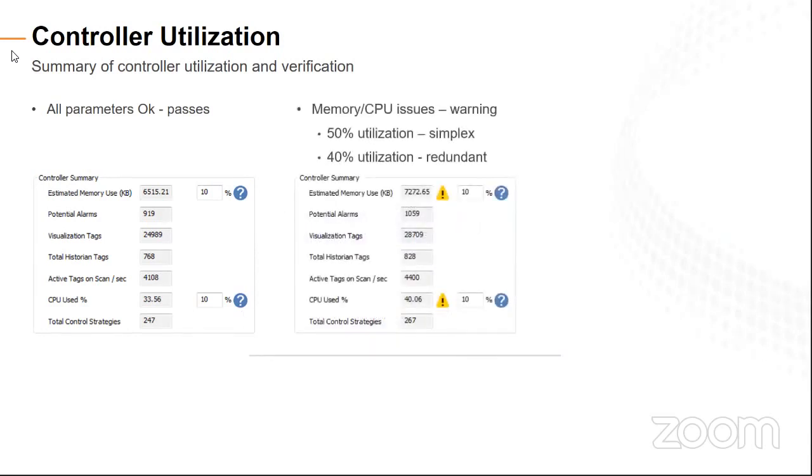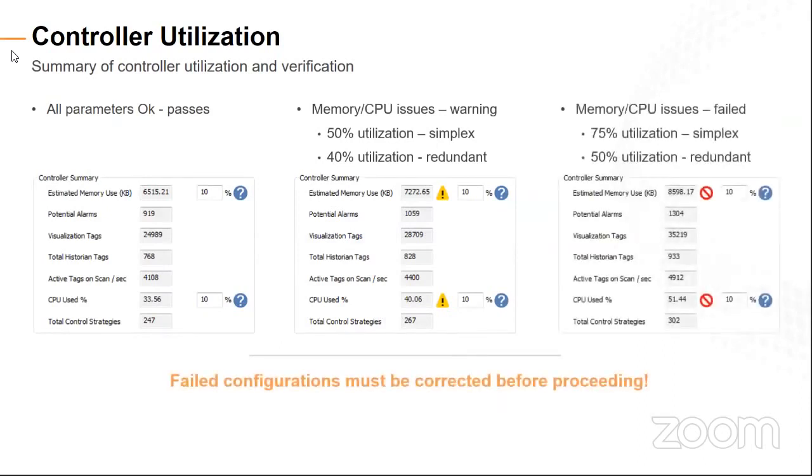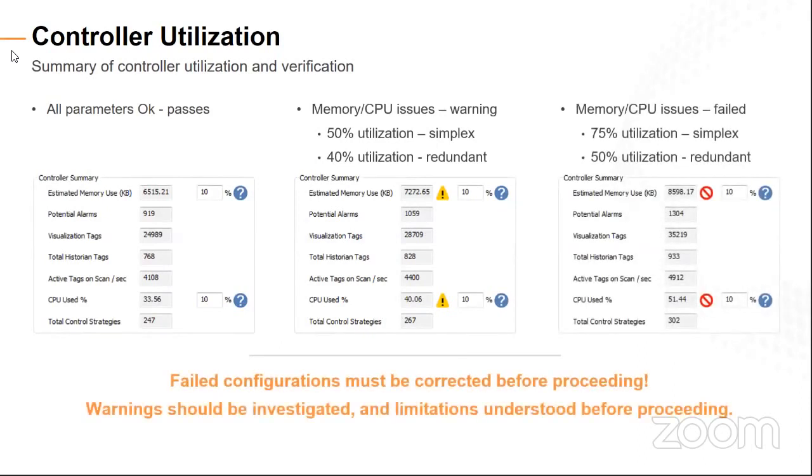So you'll start getting the warnings on there. Like I said, it will give you warnings. It'll start turning things yellow. It'll start turning things red. Red is bad. Yes. So as you start seeing, to Mike's point, you can add spares, so you can account for your system growing 1 to 5 years, let's say. So you can figure out what the loading is going to be on your controller 3 years from now when you've added another process skid.